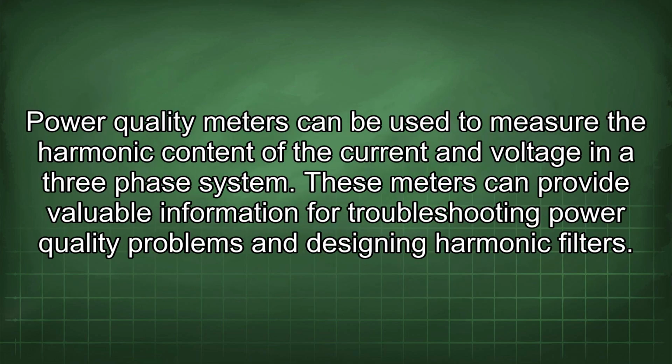Power quality meters can be used to measure the harmonic content of the current and voltage in a three-phase system. These meters can provide valuable information for troubleshooting power quality problems and designing harmonic filters.